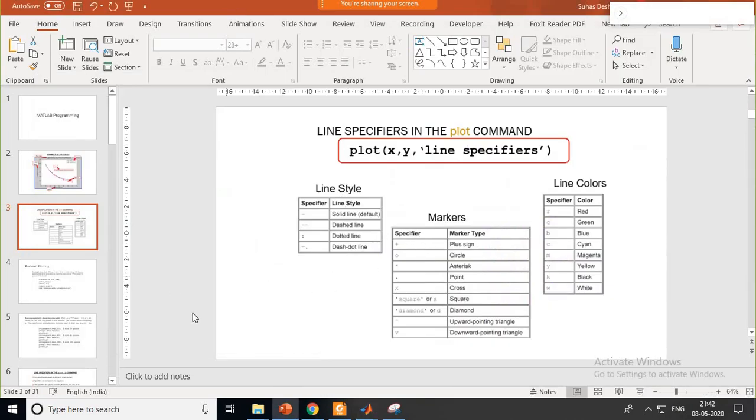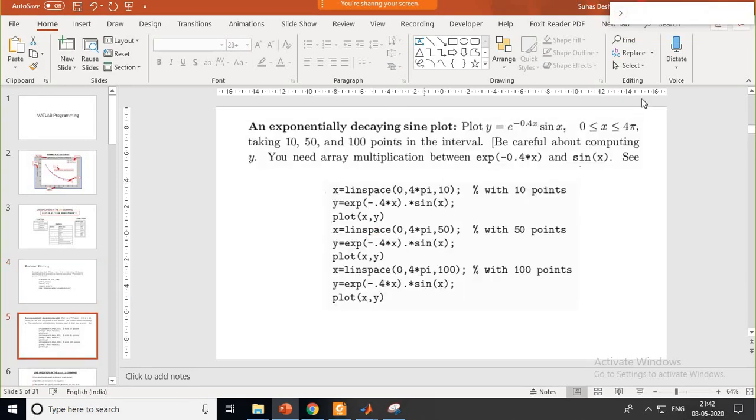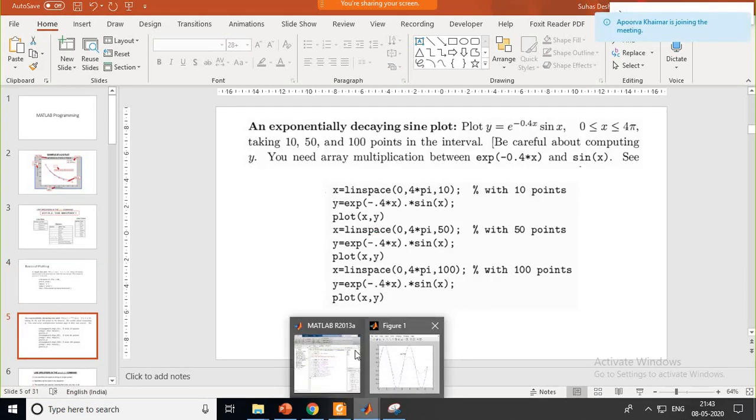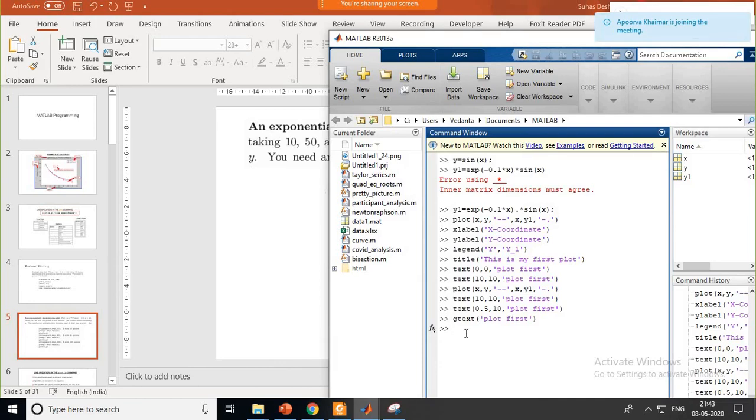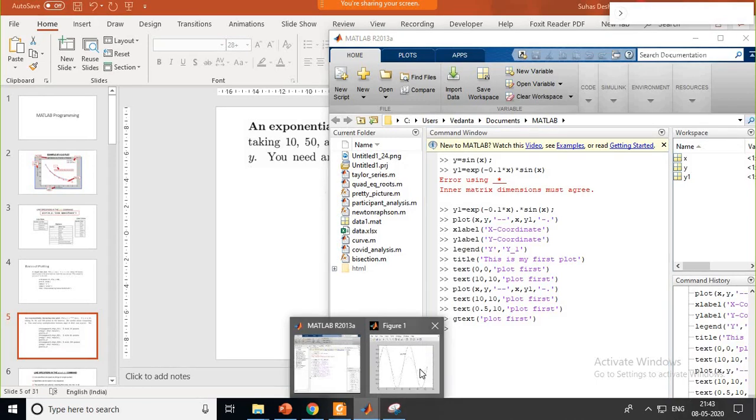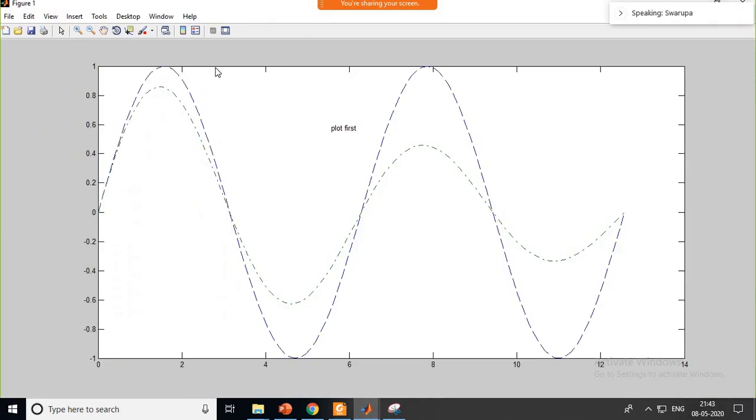After this plotting, I will go on to the next part. I will show you one more thing, which is most important: subplot. In this subplot, what it creates, this is my picture, that is my figure. So this is entirely a big figure, and on this figure I am going to divide it for multiple plots. I want to have one plot for this, a second one, a third one, and I want to arrange them into a kind of matrix. For that purpose, subplot is used.